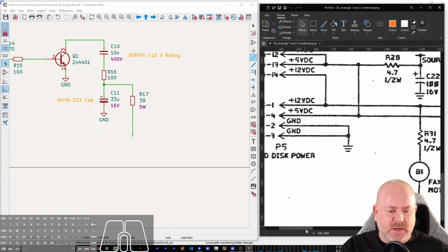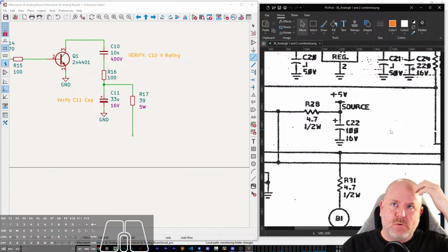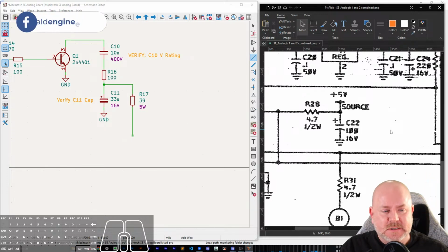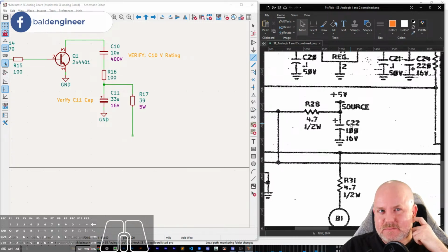And then there's other standards, like the military has a whole slew of stuff. You'll hear mil-spec, but I can't remember what mil-spec actually is. For passive components, there are the MIL-PRF drawings, each of which has a drawing number, and the drawing number corresponds to certain parts. There's also DLA drawings now, which I think supersede PRF.